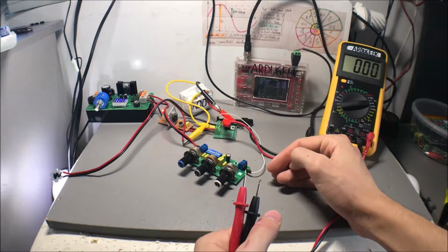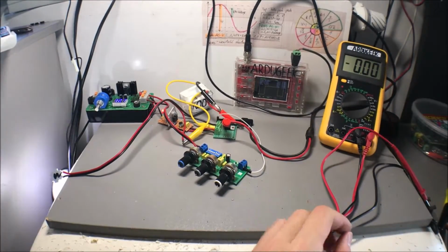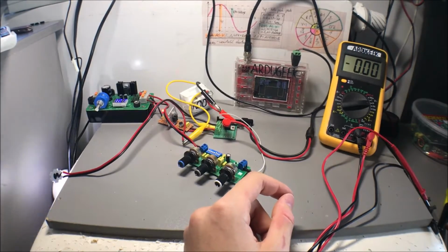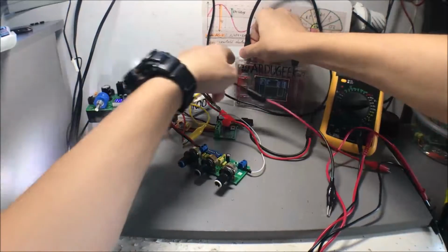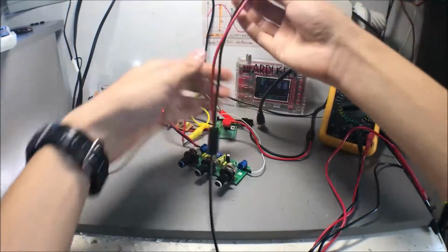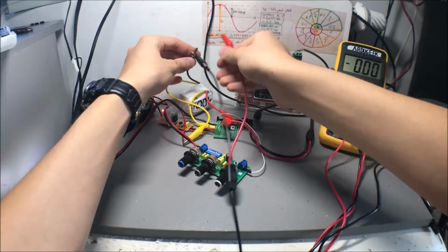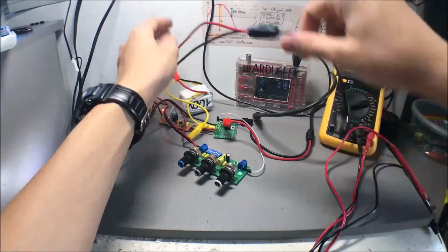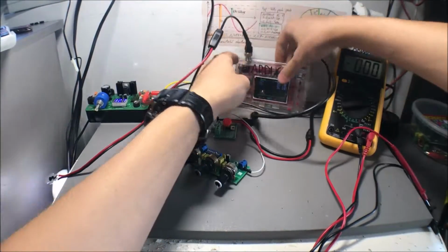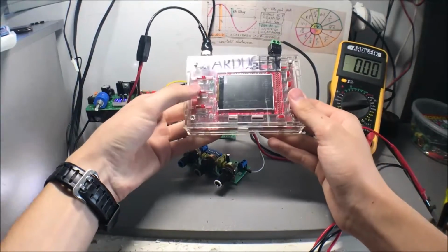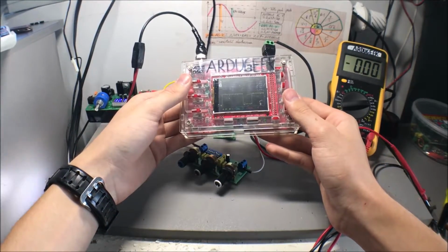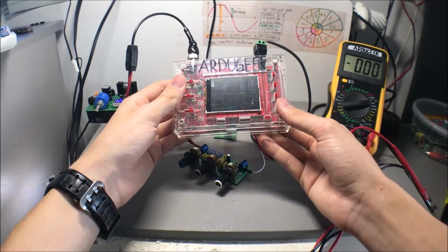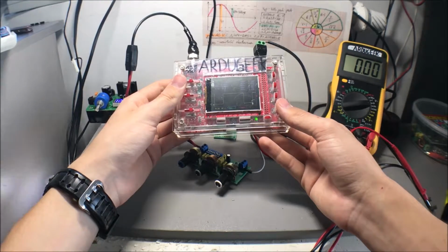But let me show you this, why not? Let's just grab a different cable, because I don't want to disconnect this one from here. Now let's disconnect this cable, clamp on with the alligator clips to the shunt, like that, and then connect all of this to the scope, and then let's measure this. And besides the whole noise that happens in here, the volts peak to peak are mainly 0.3.